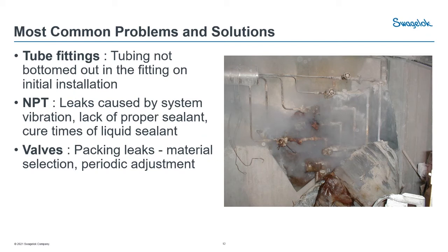And please, if you have to replace or even adjust a packing, never loosen valve packing glands when a system is pressurized, and never try to change packing out on a valve when it's pressurized. You're basically disassembling a seal at that point, and that can be very dangerous. So we want to keep an eye on that. Make sure we're never ever loosening pressurized packing glands.